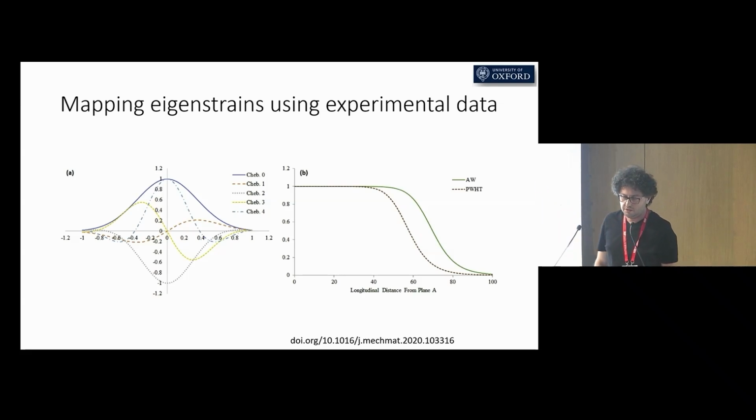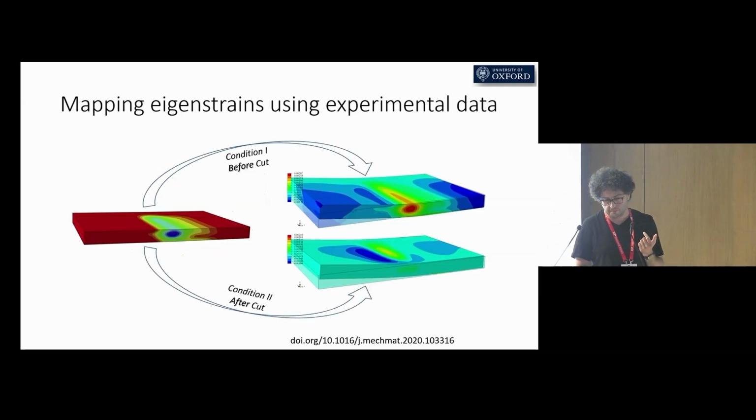These are a Gauss function to focus eigenstrain in the planar distribution, and a Hill function to focus the distribution in the longitudinal direction. Accordingly, we use in this formulation two guiding functions.